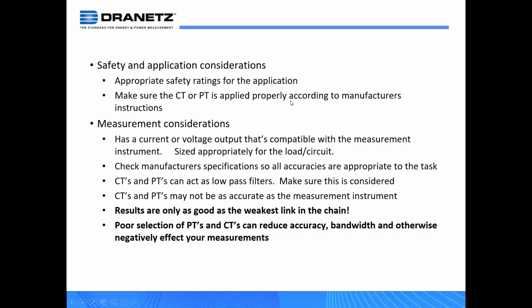I've seen scenarios where the end user will say, well, it's 4160, but the conductors are insulated. And from a measurement standpoint, you can probably get away with that, but that doesn't necessarily mean that you've taken the best safety practice in that regard. So I tend to be conservative in those areas. You want to stick to the manufacturer's instructions and don't try taking shortcuts.